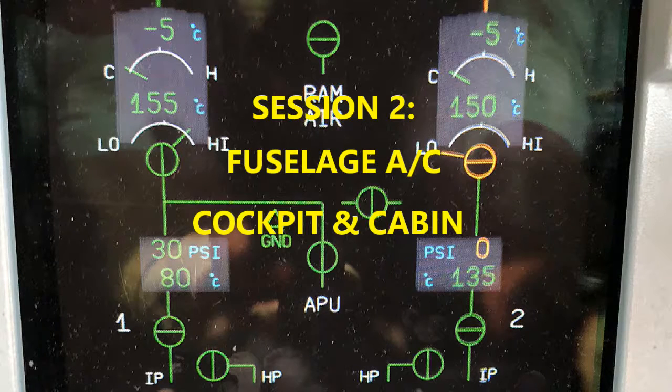And so what triggers the anti-ice valve to open? Okay, it's going to be the sensors. We've got a delta P sensor, or two, one for each. So we've got delta P sensors of the anti-ice valve that you can find across the condensers. And they open if those sensors find an unusual difference. If there's a pressure differential across the condensers, then the anti-ice valve is going to open.